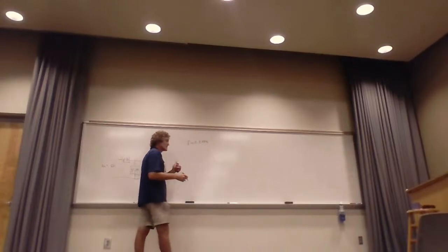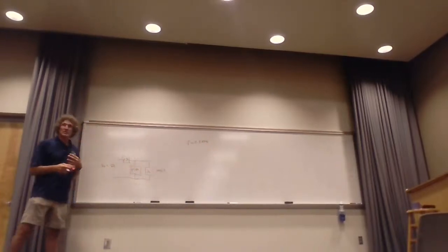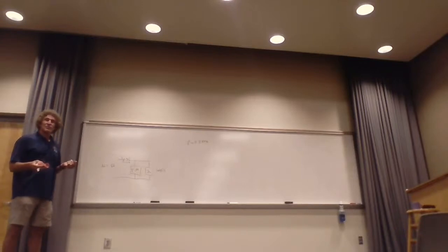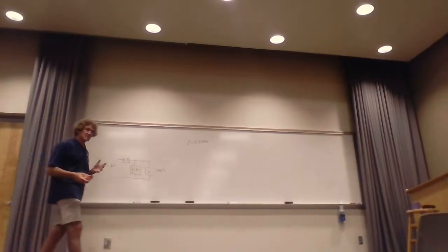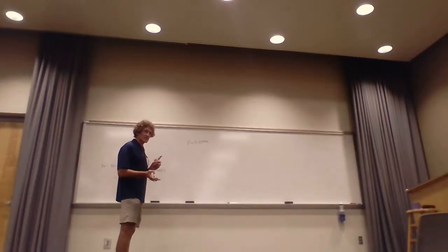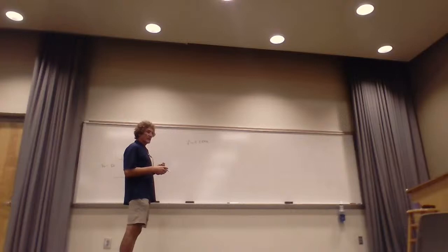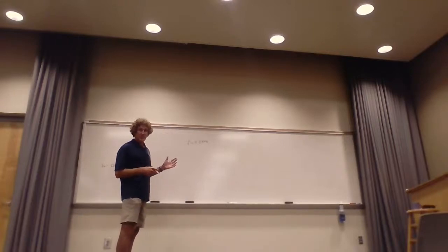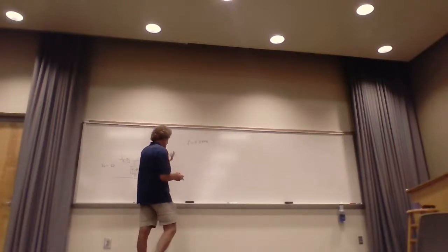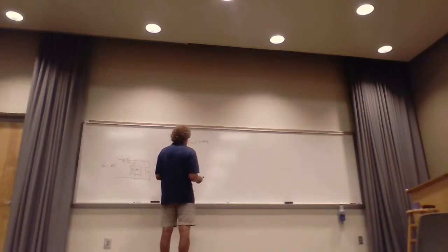By the way, that range right there is so typical. Wi-Fi is what, 2.45 gigahertz, right? Anywhere around the 2 to 3 gigahertz range, a zillion tons of stuff you do in engineering is in that frequency range. Up around 10 gig, you get lots too, and then around 33 gig, and now 77 gigahertz for automotive radar. So those kinds of microwave frequencies are very common. Anyway, 2.5 gigahertz is very common. So we're going to deal with this one first.